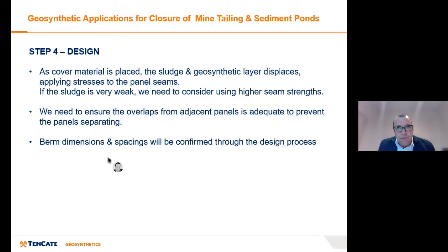For example, in situ seaming, you can do trials, and you might be getting 30, 35%, maybe 40% of the strength across the seam, depending on the capability of the stitcher. In the factory, depending on the capability of the teams, you can get north of 50%.